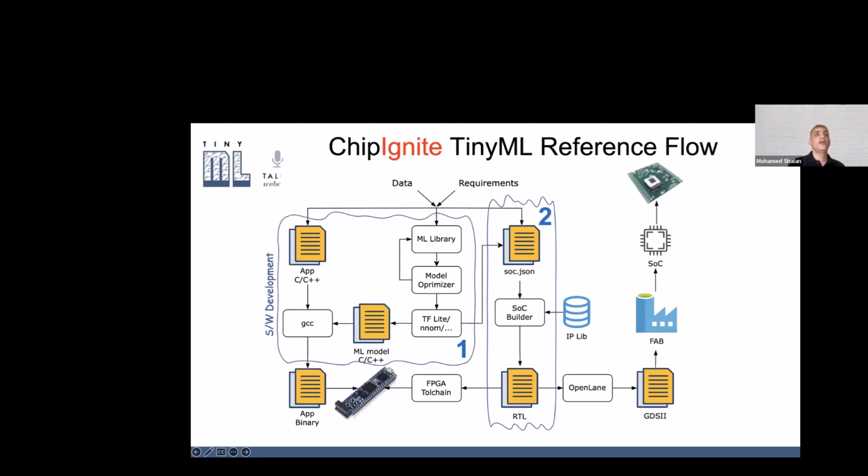Once you have the RTL, you can perform FPGA validation, where you have your RTL implemented into the FPGA. Your software that includes the machine learning model will run on top of your SoC design, which is mapped into the FPGA, and you can do validation of the SoC that was generated for you even before going for fabrication.